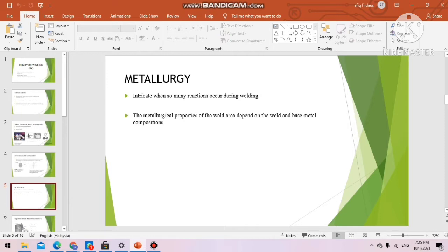The fusion zone microstructure is very dynamic and is extremely sensitive to the different welding parameters such as amperage used and the weld start and lift-off period. The welding parameters correlate to phase shift and solidification behavior as well.